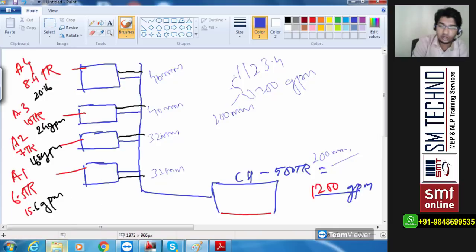So with 4 different connections to the AHUs, the main riser size is going to remain the same, 200 mm, because the water content is reducing, but the size depends on whether the GPM goes down substantially. So now the question is, what size should we keep for the riser after supplying the different AHUs, or from the start?